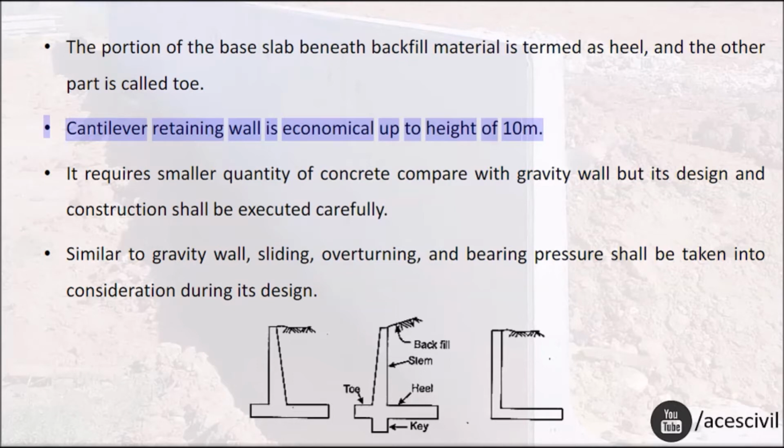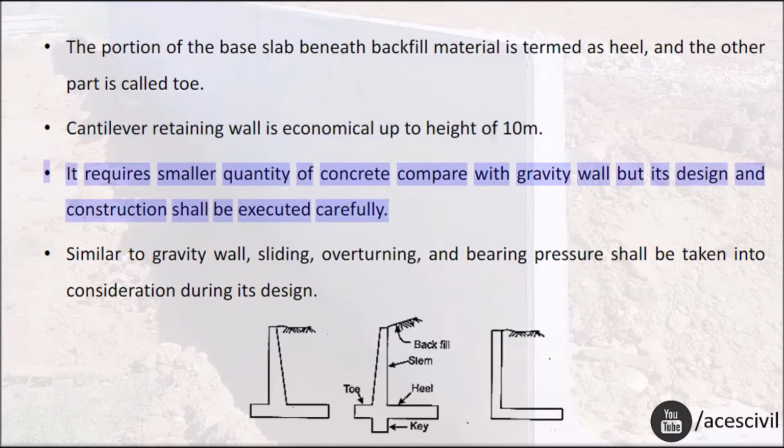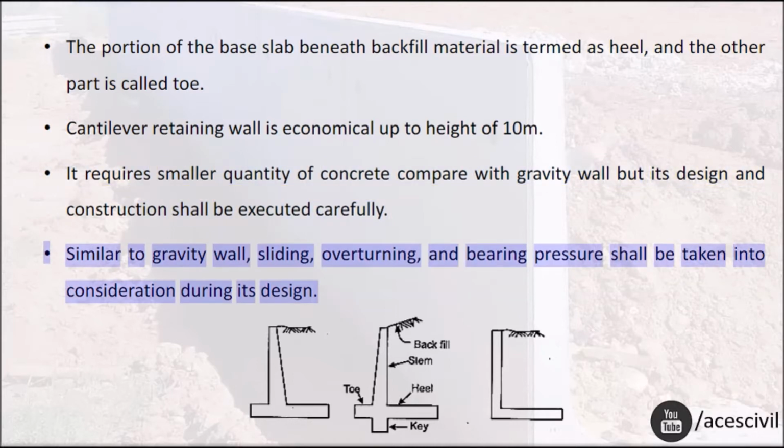It is economical up to a height of 10 m. It requires a smaller quantity of concrete compared with gravity wall, but its design and construction shall be executed carefully. Similar to gravity wall, sliding, overturning, and bearing pressure shall be taken into consideration during its design.